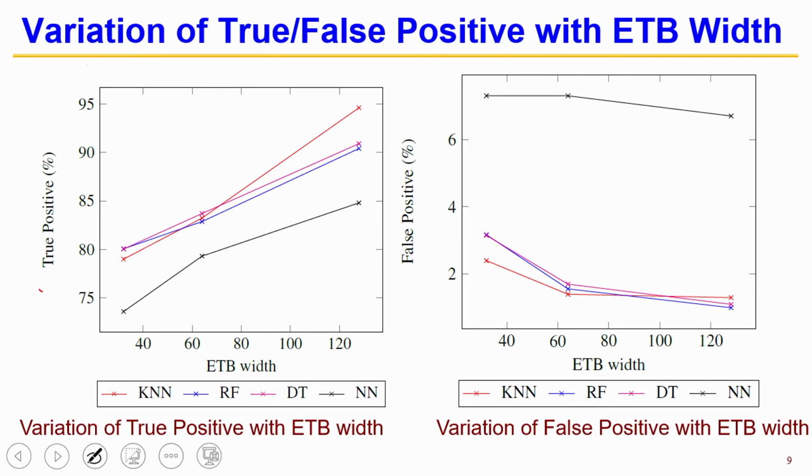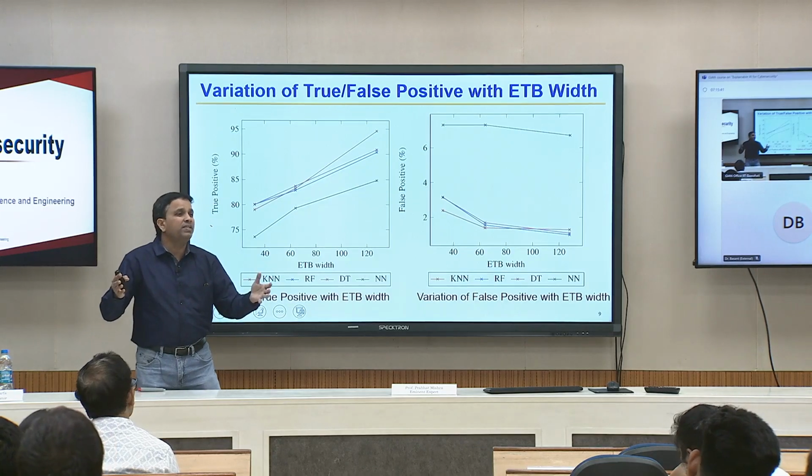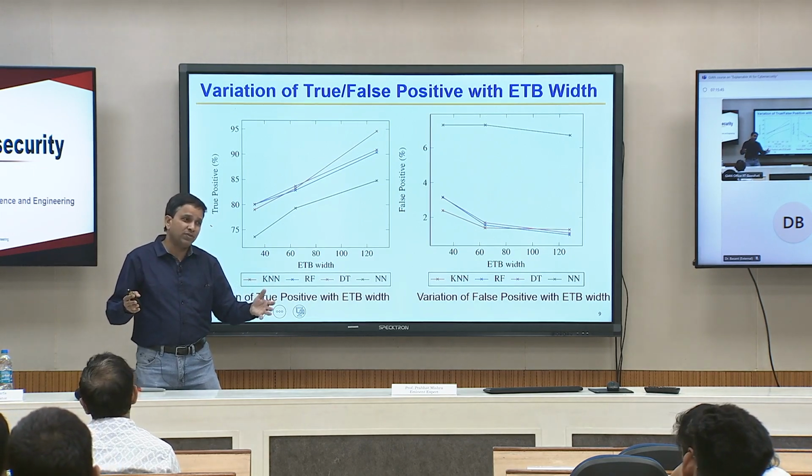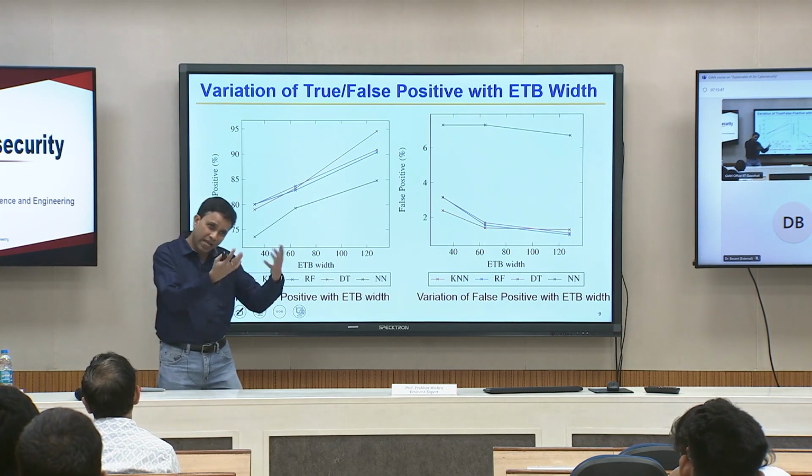So, basically that is how you decide which model to use, you decide how much data, what size of design I can use, sometimes you do not have a choice. This particular one makes the assumption you have control of telling the processor designer what size of ETB, embedded trace buffer, they should put in. Most of the time you do not have that choice, you have to stay with whatever design it came with.